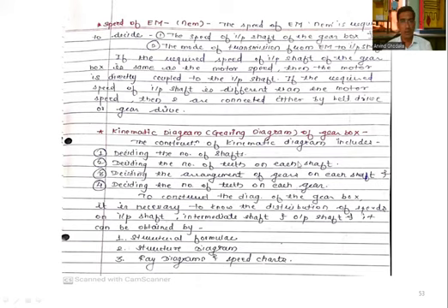The construction of a kinematic diagram includes deciding the number of shafts in the gearbox, the number of gears on each shaft, the arrangement of the gears on each shaft, and the number of teeth on each gear. To construct the diagram of the gearbox, it is necessary to know the distribution of speed on the input shaft, intermediate shaft, and output shaft. It can be obtained by using the structural formula, structural diagram, ray diagram, and speed diagram.